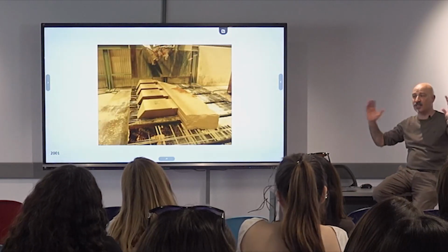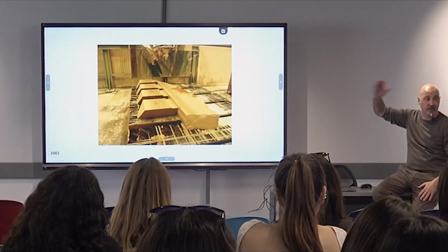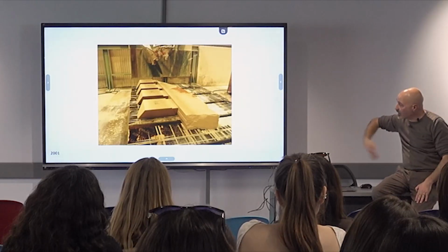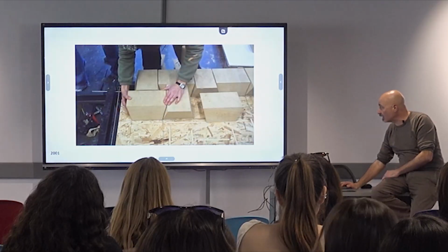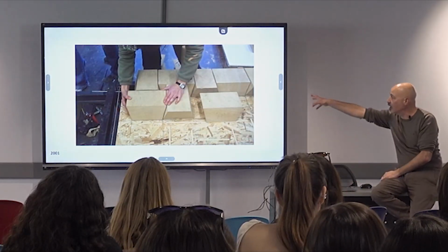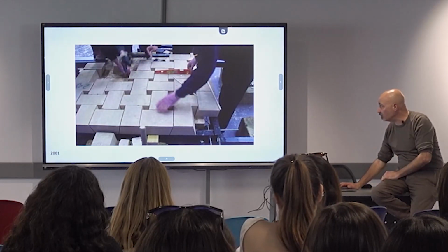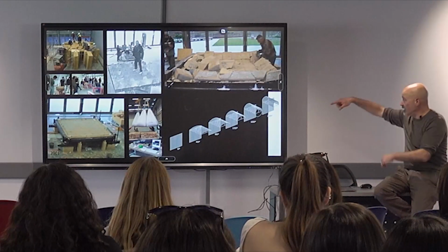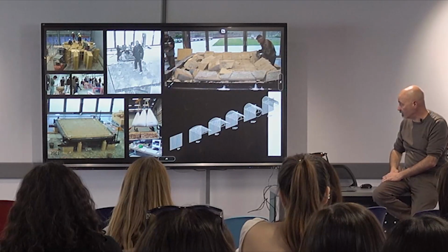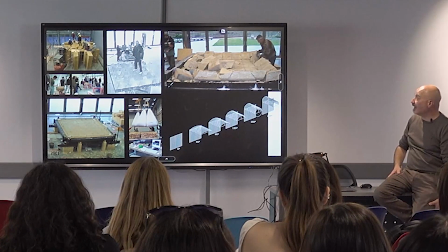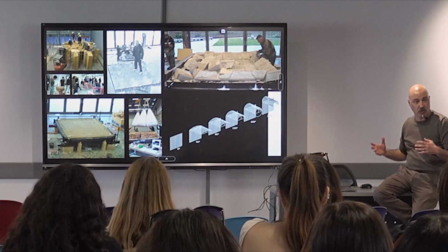A very easy realization. We start from a parallelepiped. We take the inclination of the machine. We cut in an easy way from one side to the other side. And once all the blocks are ready, we start to assemble in a vertical and horizontal way. And in very little time, everything is ready. We need the border part to take the pressure of the stone, and we make the first crushing test of the vault. It was very, very hard to destroy the vault.